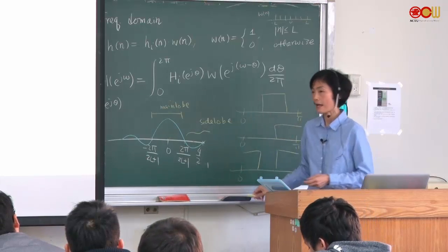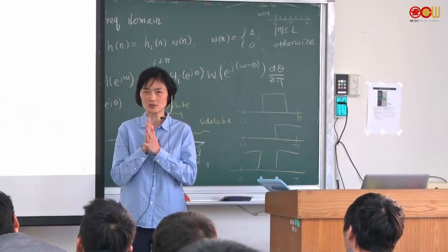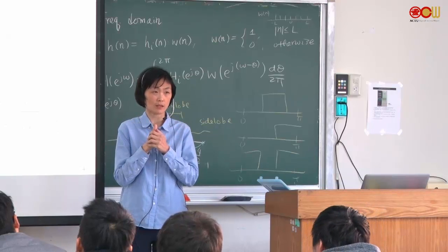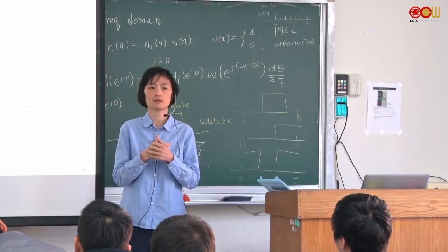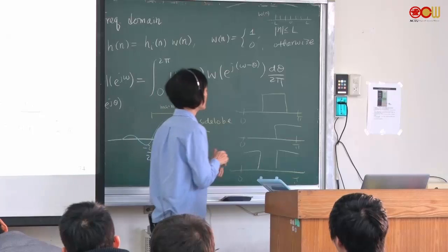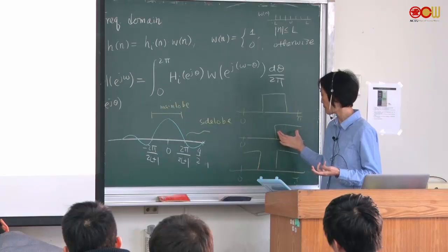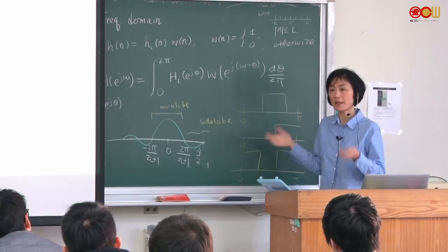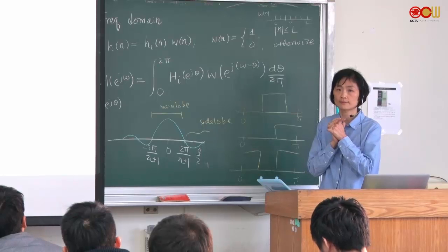Like so. Okay. And in the MATLAB that we are going to do, have you had the chance to look at the MATLAB file? Well, we have this jammed signal, right? And you probably need to look at the properties in the time domain and frequency domain to determine what kind of filter you need. Is it a low-pass filter that you need, or a band-pass, a high-pass, or a band-stop filter? Okay, depending on the noise that's used to jam the signal. All right.